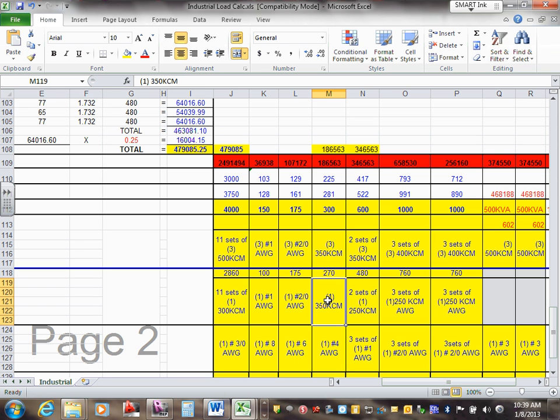That's a rule that we apply for the neutral. And instead of adding the neutral current like we did detailed, you still can't do that. I mean, either way will work. But we did it in the commercial project. We have an item for the neutral. The project becomes bigger. Like you can see, there's so many other panels. We're interested in the bigger picture. And when you get higher amps, guys, the neutral becomes not a big of a deal.